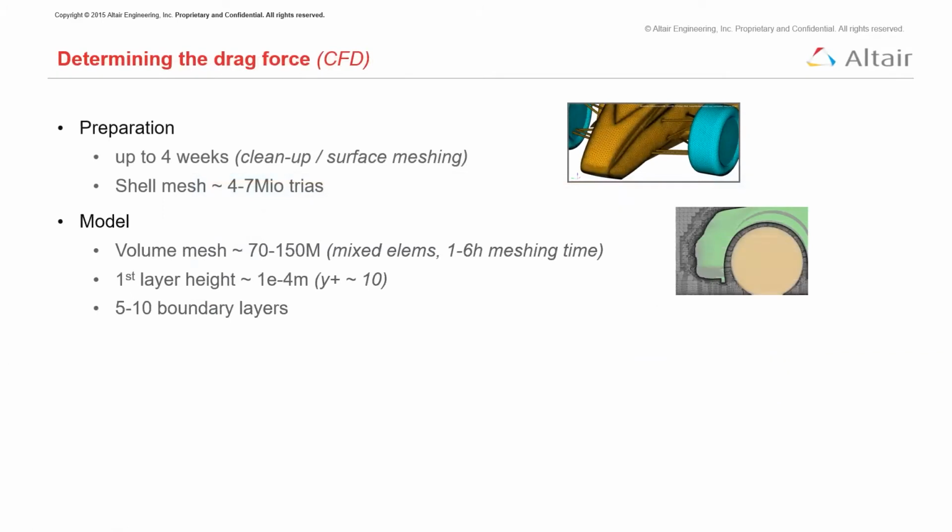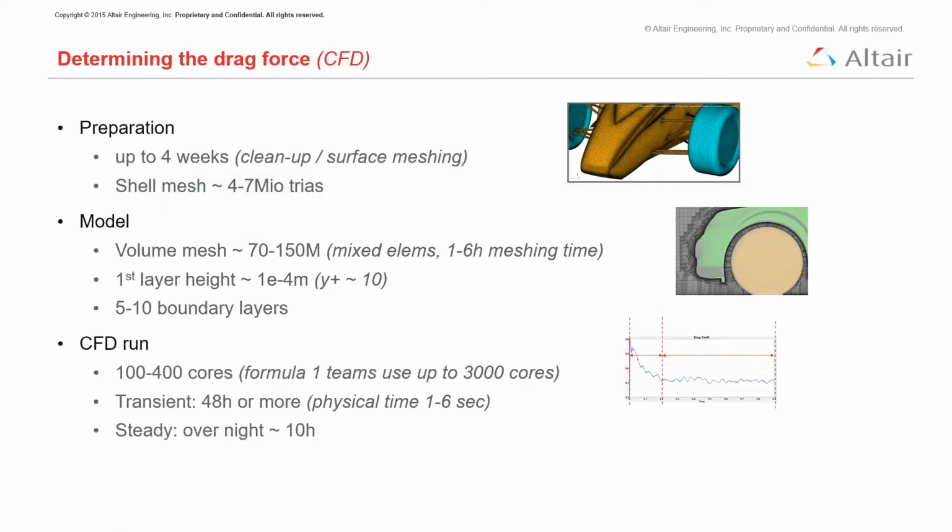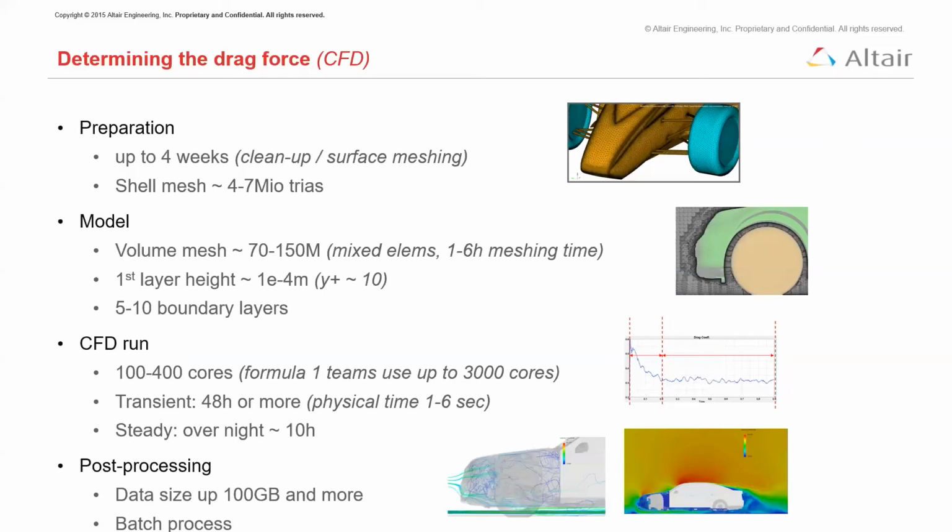All right, so here's kind of the steps we take to run a typical CFD model. Again, some of these numbers I don't want you to take to heart. It is flexible depending on your use case. But for an automotive case, again, typically it'll be up to 4 weeks in industry for cleanup and surface meshing. That's just prepping your model to bring into CFD.